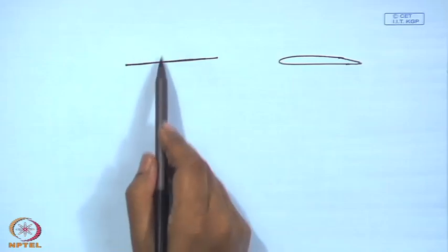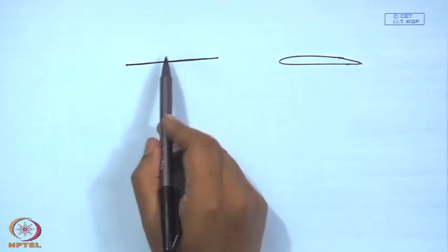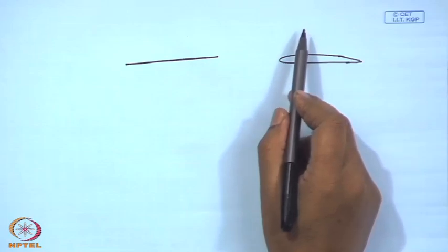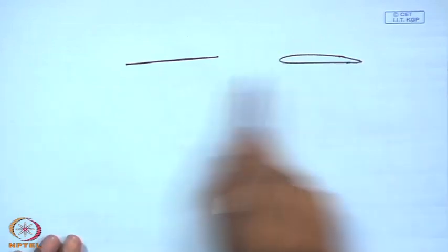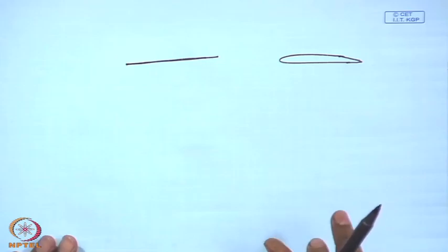They are opposing each other. Similarly, in the sideways, viscosity is trying to spread it in this direction, while convection is trying to carry it along with it. As we mentioned, the normal component of velocity being small, the convection in the normal direction is much smaller than the convection in the streamwise direction. So, even on these two sides there is practically an opposition between diffusive spreading and convective spreading.